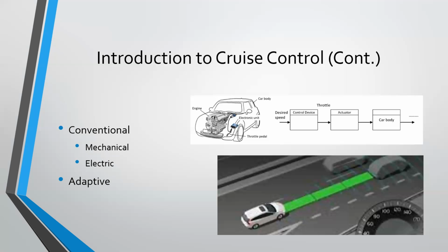Newer vehicles have adapted to a drive-by-wire design. In this design, the throttle pedal is no longer connected mechanically to the throttle body. Instead, the throttle pedal is attached to a potentiometer or transformer, which alters an electrical signal. This signal is interpreted by the vehicle's engine control unit, or ECU, which lets the vehicle know where the desired throttle position should be.